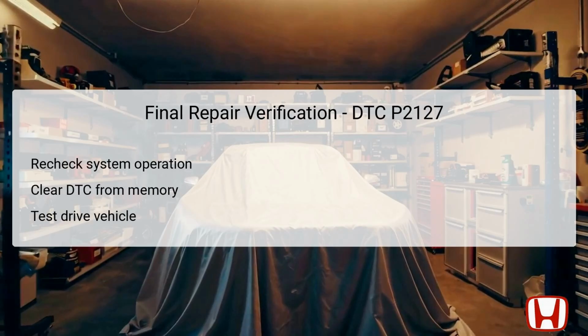After completing all necessary repairs related to DTC P2127, it is essential to verify that the system is functioning properly. Begin by ensuring the system's operation is restored and the APP sensor is delivering accurate signals. Clear the DTC from the vehicle's memory using the Honda Diagnostic system, which essentially resets the onboard computer.